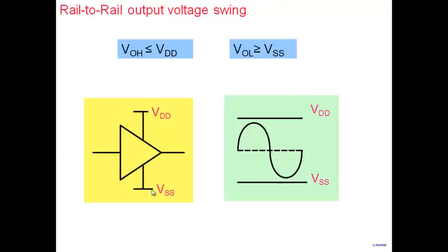And in this context, I've shown an amplifier here which is driven by a positive power supply, which is VDD, and a negative power supply, VSS. For example, your 741 op amp, we typically apply plus 12 volts here and minus 12 volts here. Now at the output, typically we would like it to go as far on the positive side as VDD. In a good amplifier, you could drive the output voltage almost towards VDD, and similarly, on the negative side, almost to VSS.